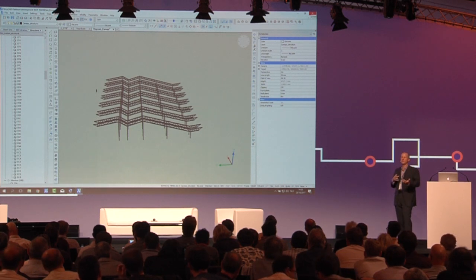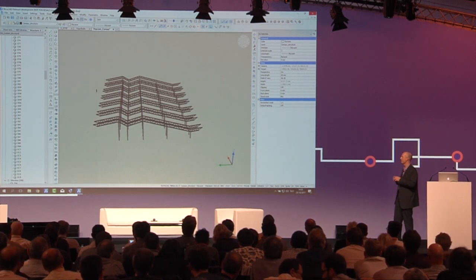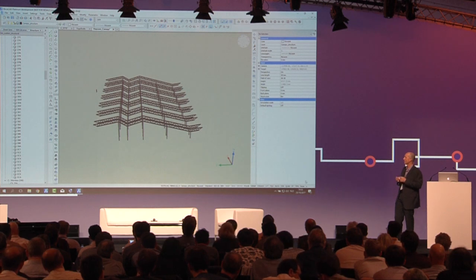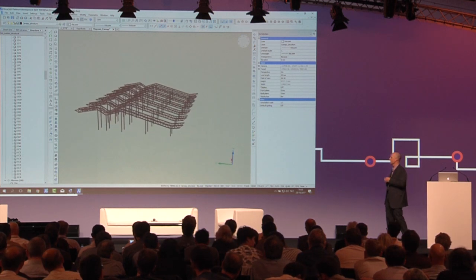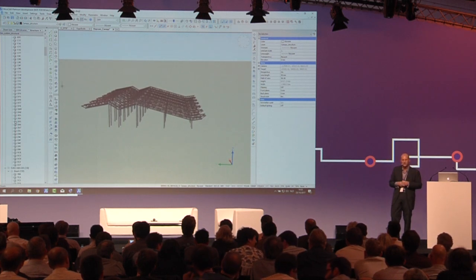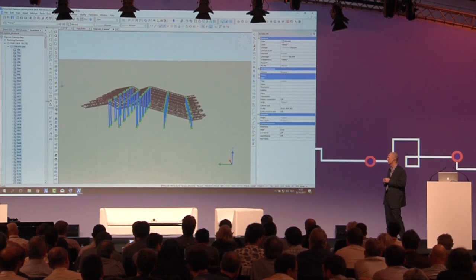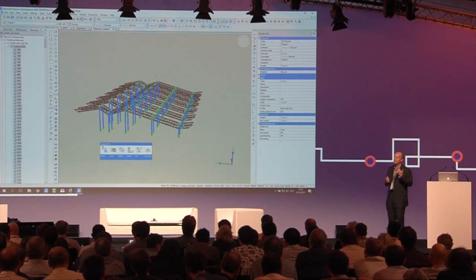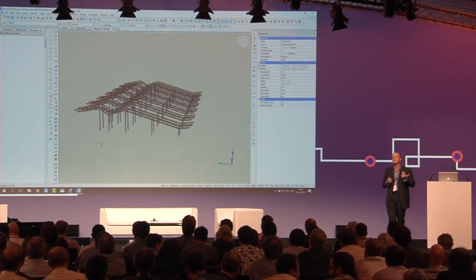But also, having experience with the structural engineer we work with, we know that they tend to enjoy larger columns. So what we can do is select all the columns in this overall structural layout, and we can do BIM apply profile to that.